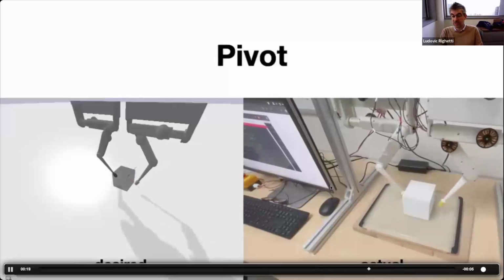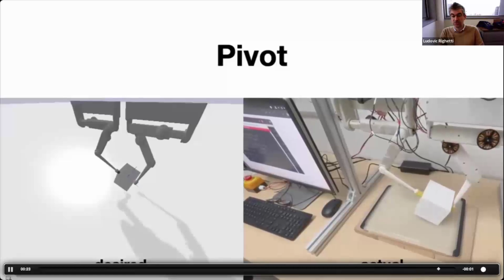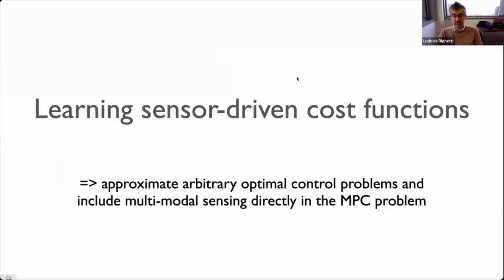You can do different things. Another one that I think is actually not so easy, if you want to be able to execute it on the robot, given the bad model and all these things, you can plan what kind of contact and force you need to apply such that you can balance a cube. You can do that in a second. You can plan this thing and then execute it on the robot. So we're getting close to interactive real-time rates for planning contacts using our models, especially leveraging the fact that we can learn things offline in advance.